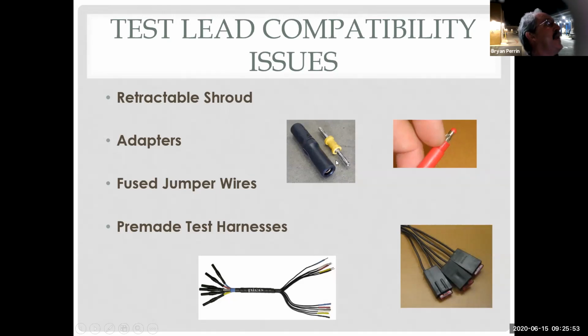So these are called a banana plug lead. There's 2 main kinds of leads we use on scopes in automotive. One is a banana plug, which is what we see there. It's a 4mm banana. The other one is called a BNC, and that is shielded. It goes on and it twists, so it looks more like a single wire, even though it's 2. It goes to a coaxial cable, and it has little ears on one. You slide the ears over and twist it to lock it. Those are the 2 types of scope leads that we use in auto. Almost all of our equipment we use at ECC uses the banana leads.